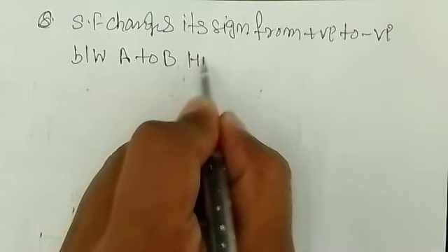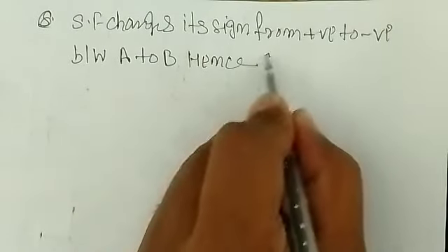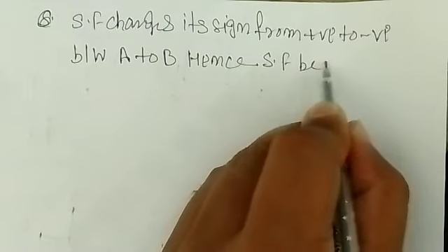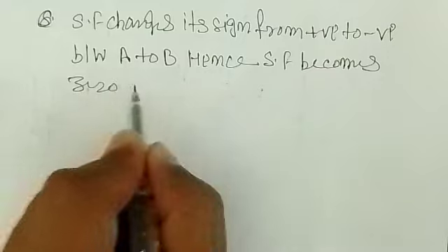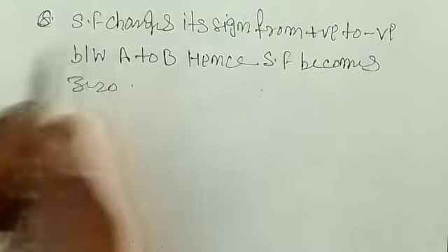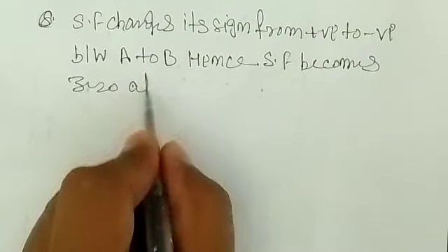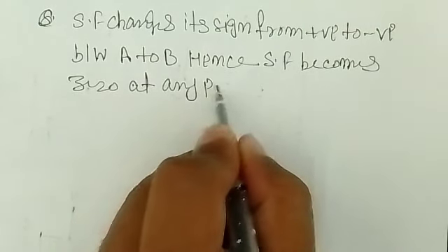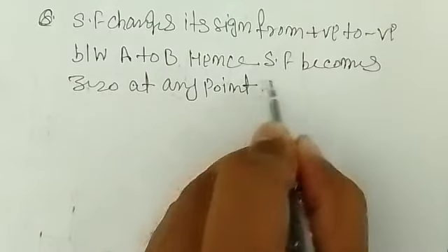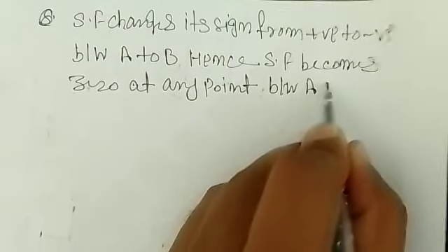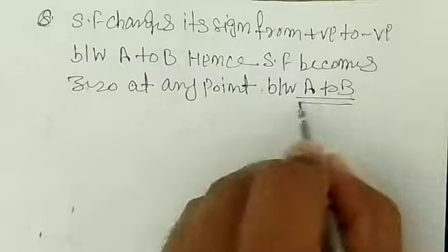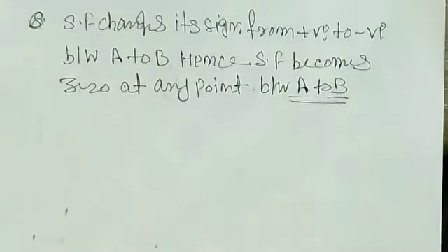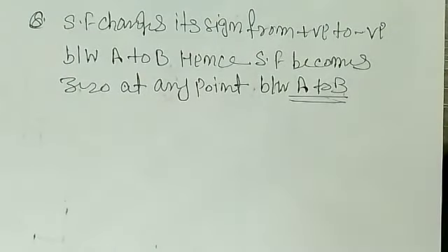Hence the shear force becomes 0 at any point between A to B. So it means that wherever the shear force changes from positive to negative, there must be one point where the shear force becomes 0. That point we have to locate.